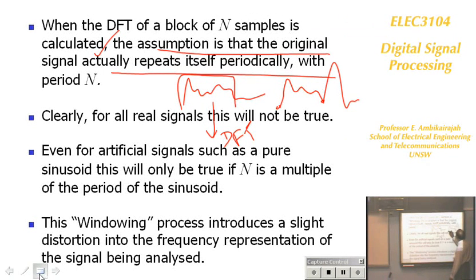That's what the DFT assumes. So you can see naturally the original signal was nicely continuous. At that point, this has to start again. So there's a discontinuity you are introducing. That is a problem in the DFT. When you take 100 samples or 1,000 samples, you're truncating the waveform, and the DFT assumes that waveform is repeating. That's the assumption of the DFT.